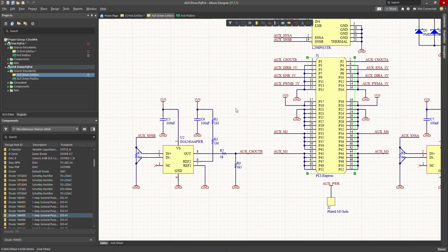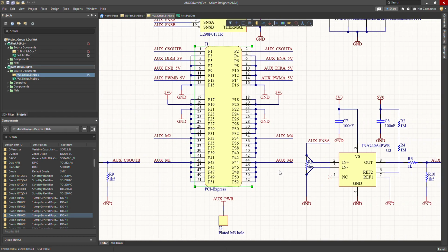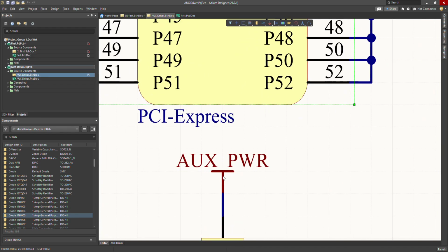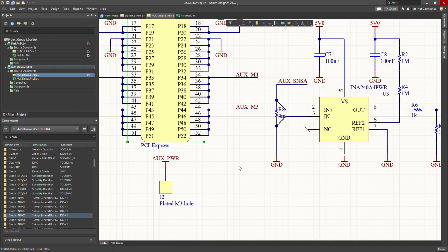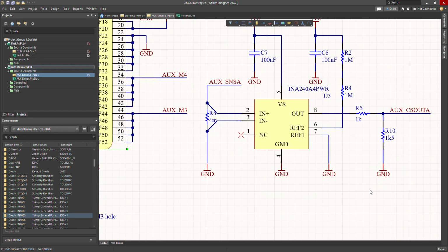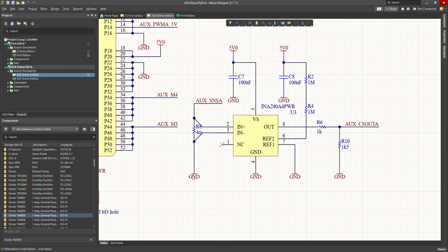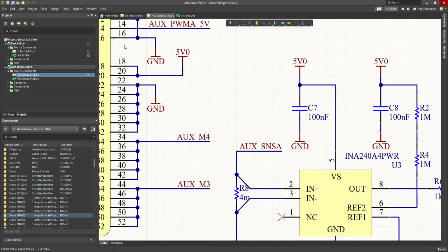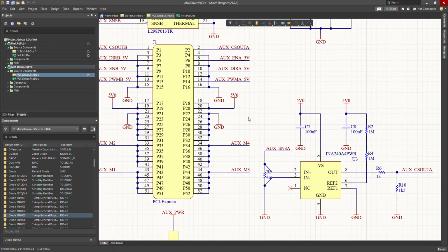In this case, it's just 5 volt, and it's 5 volt also here and 5 volt here. This is another power port. As you can see, it has this symbol that shows this is a power that is not ground. And another nitty-gritty thing to keep in mind, we usually try to keep the designs clean so it's readable. We want the grounds to be in the same line, and always the grounds are going to be facing bottom, and the powers are going to face up. So like you can see that the ground is facing down and the 5 volt is facing up and all that. So those are the power ports.